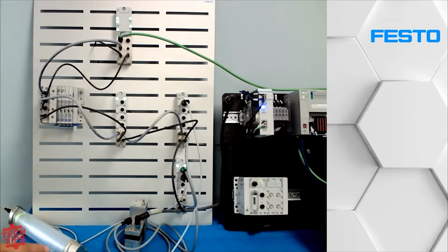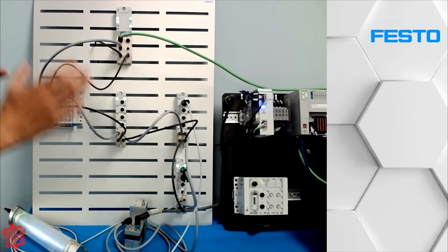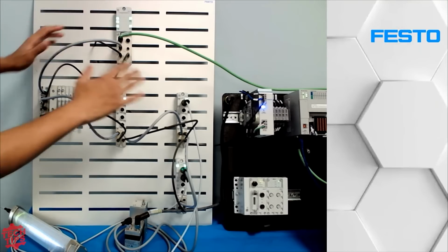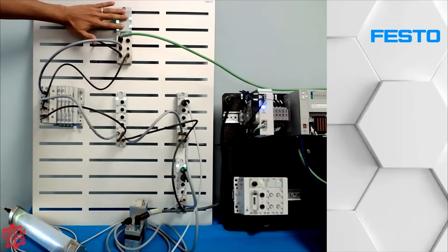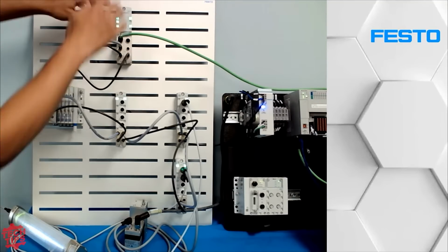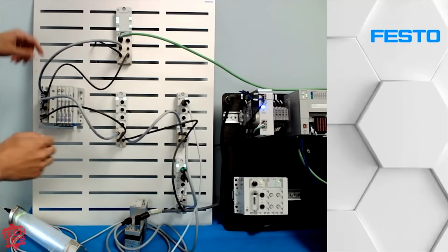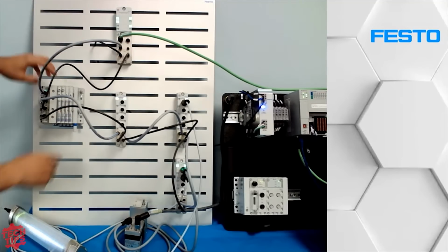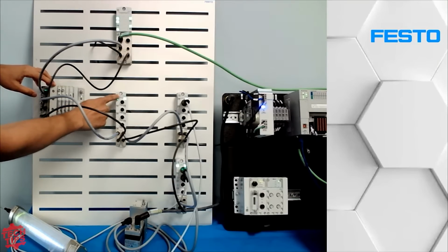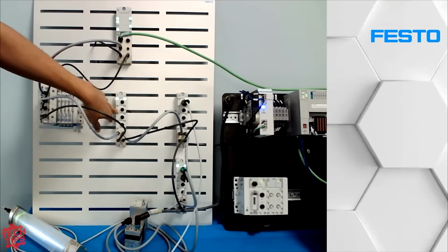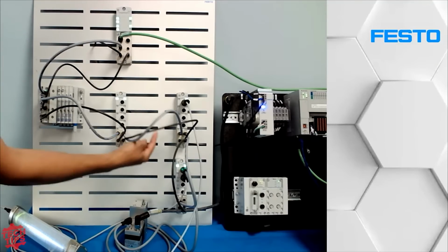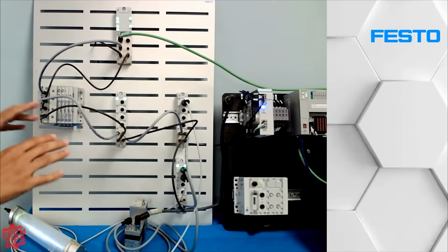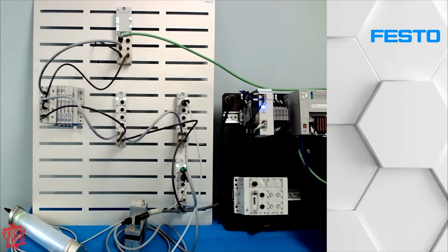Now, you mentioned DIP switches, and that's a really good question, because in the past, this was the way of setting up these kinds of devices. But now, once I have everything connected, all of the power and communication cables, I power up this module, and this is the beauty. This module pings everyone that's connected to it and says, who are you? Who are you? And so on. And then one says, I'm a valve manifold. This is a 4 digital input, 4 digital output module with M12 connections. I'm an 8 digital input module, and so on. So on power up, it recognizes everyone that's connected to it, so you don't have to set anything on who's who.